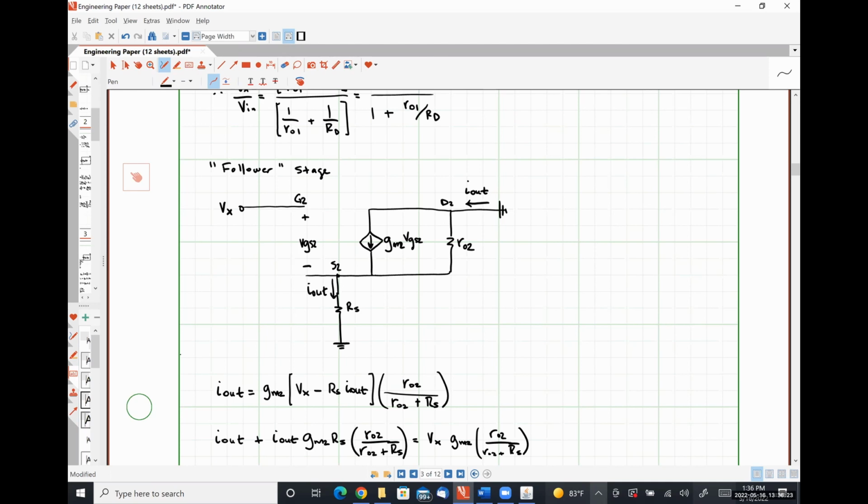That's why I was confused. Right, yeah, but because it's not a voltage amplifier is why I wouldn't consider it to be a common source amplifier. Because in a common source amplifier, you're 100% correct, we apply the input voltage at the gate and we measure the output voltage at the drain. But because this isn't a voltage amplifier, I was just trying to figure out something that it looked the closest to, and to me, that would be a source follower.